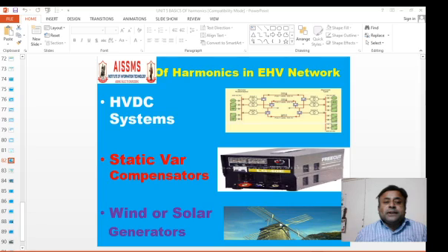Then we have seen what the detrimental effects of harmonic distortion are. These detrimental effects are overheating, failure, incorrect reading, undue tripping, and so on. Equipment like motors, transformers, circuit breakers, and generators fail because of harmonic problems. System improvement devices like shunt capacitors, APFC panels, or even synchronous condensers are also victims of harmonics a number of times. Therefore, it is necessary to mitigate harmonics.